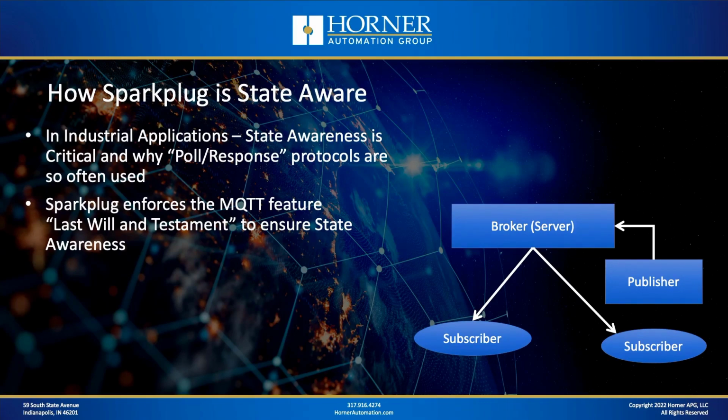But now let's talk about some of the changes that were made to Sparkplug, the supplements to the specification that allow it to work well in industrial applications. We're going to start with state awareness. So what is state awareness? That is where, as a subscriber of data, monitoring data for whatever purpose, you need to have awareness as to whether that is the latest data and that the device that's publishing that data is online effectively. And so you're confident you're looking at the very latest data.